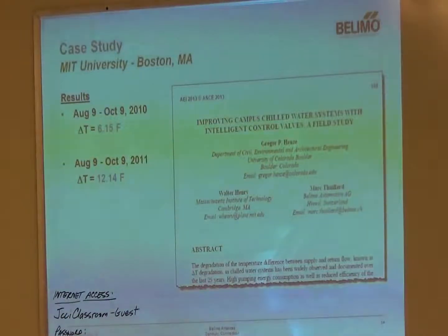Yeah, yep. And they've done a study on the chilled water side of their loop, and if they were to go in and replace a fixed valve with a PI valve or an energy valve, they're estimating about $1.5 million savings a year. So, you got a big campus, you got a big system, your numbers can really add up quick, and then it really just depends on how your system's been maintained and how well you control it.